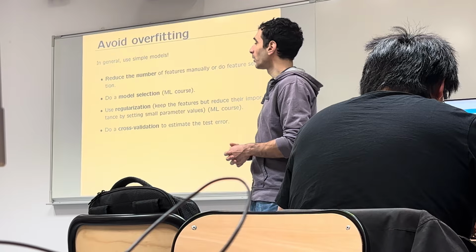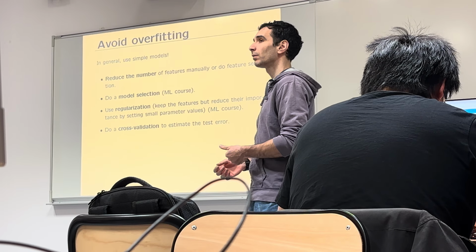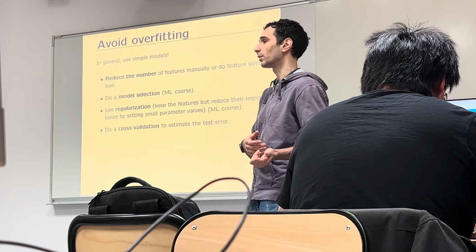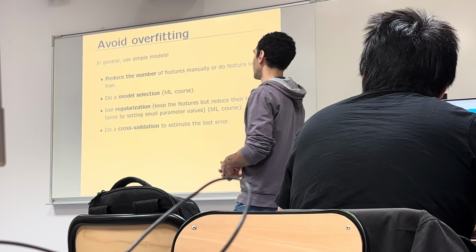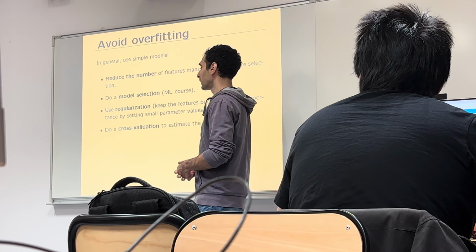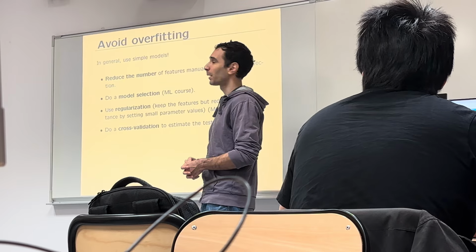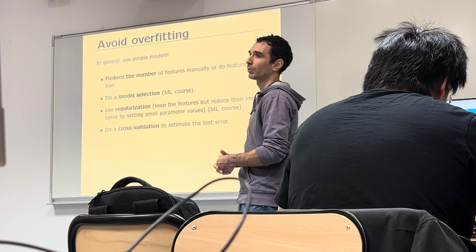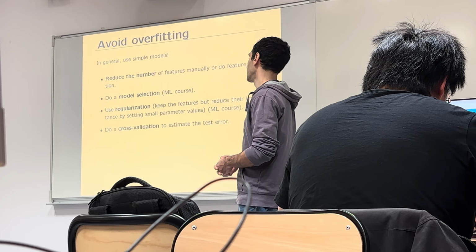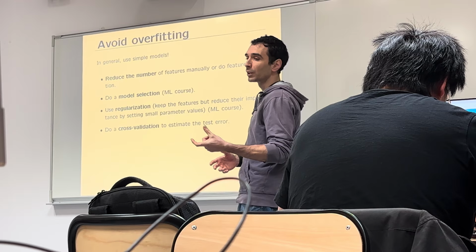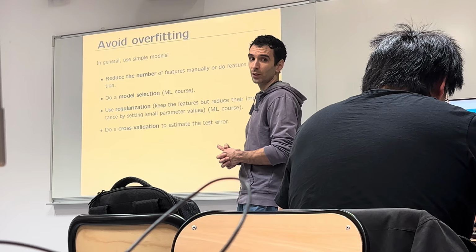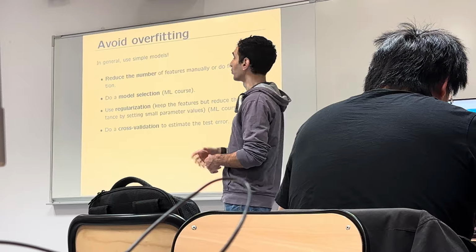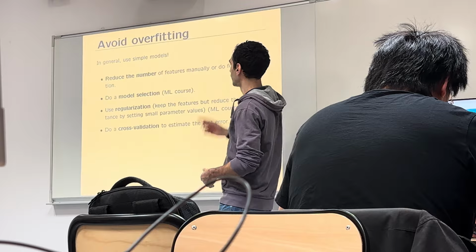Actually, the temperature during concrete mixing is not that influential on the compressive strength at 28 days. Maybe it can be relevant if the temperature is ranging from, I don't know, -10 to 40 degrees. But most of the time, if it's ranging from 10 to 25 degrees, as we have here, it's not useful at all. So you should just get rid of this information.